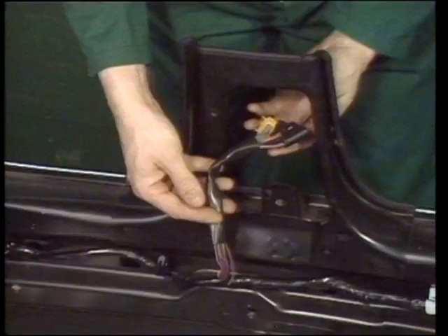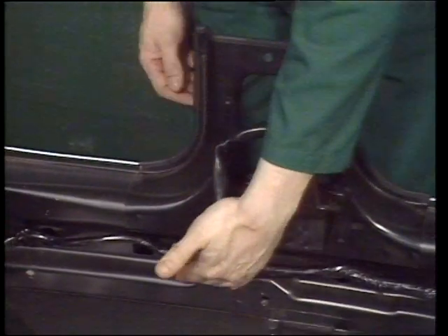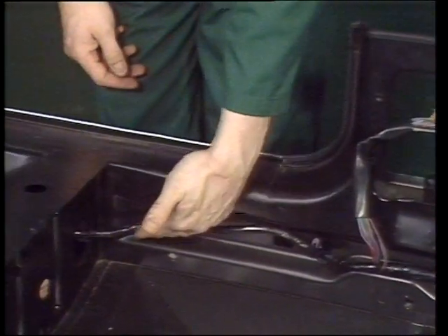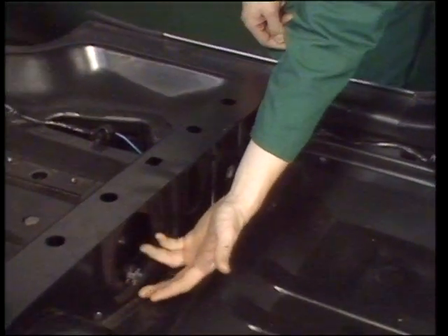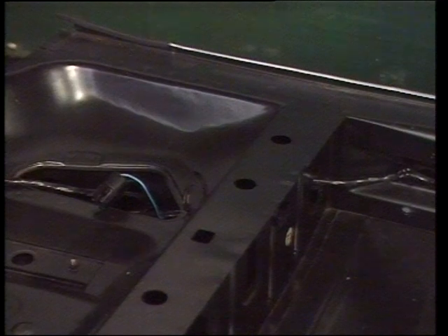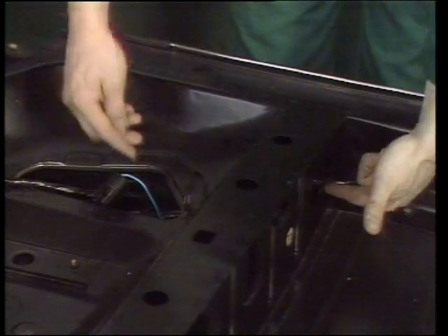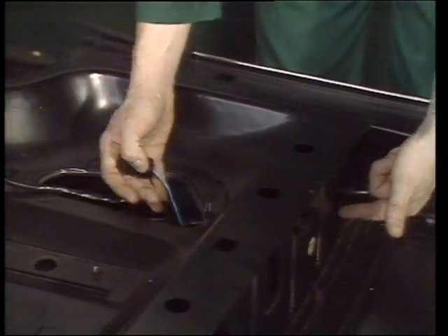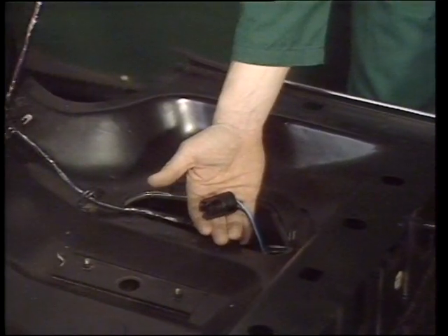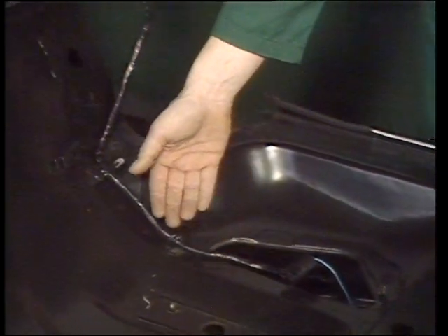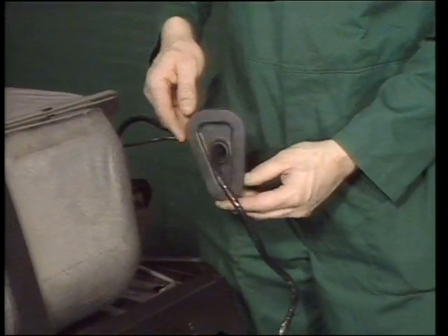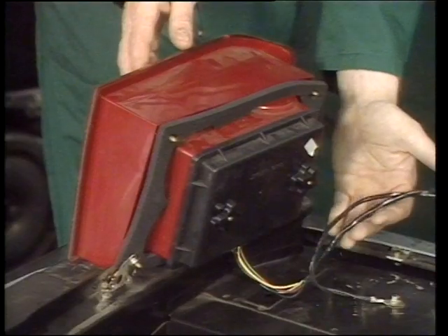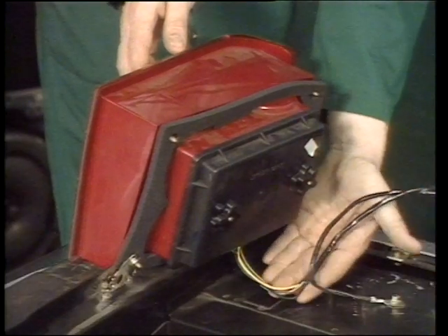The side harness continues to run recessed into the sill up to the rear seat pan, where it's run into the heel board. There's a breakout at the heel board for the heel board speaker. The side harness continues to run under the rear seat pan, allowing another breakout which carries the connection for the fuel pump. The rest of the harness runs onto this grommet, which will be positioned in the D post. It then passes through the baffle plate grommet into the boot, where the side harness run finishes.